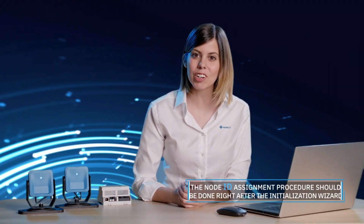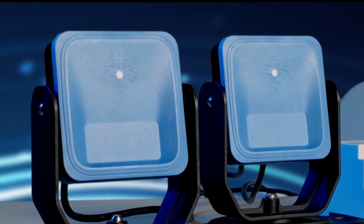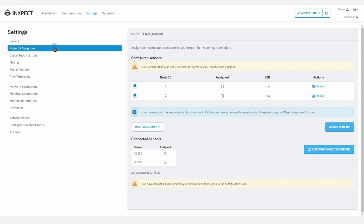The Node ID assignment section is where each connected sensor gets its unique identifier, which in turn allows the control unit to recognize and identify the sensors along the chain. You can quickly recognize sensors without an identifier. Their LED will flash twice. There are three ways to assign the node ID to a sensor: automatic, semi-automatic, and manual. Let's start with the first two.